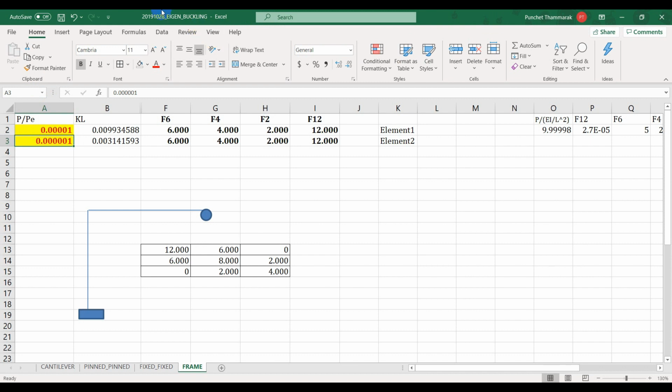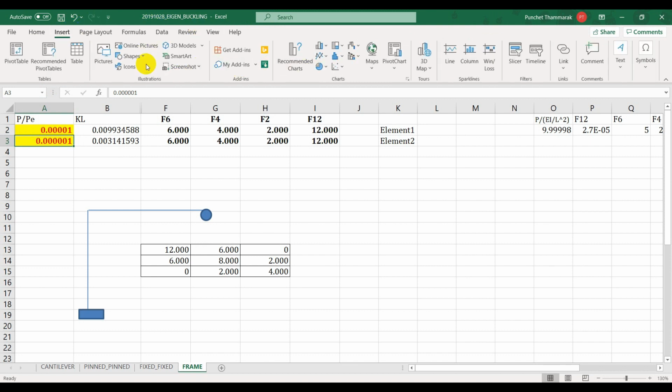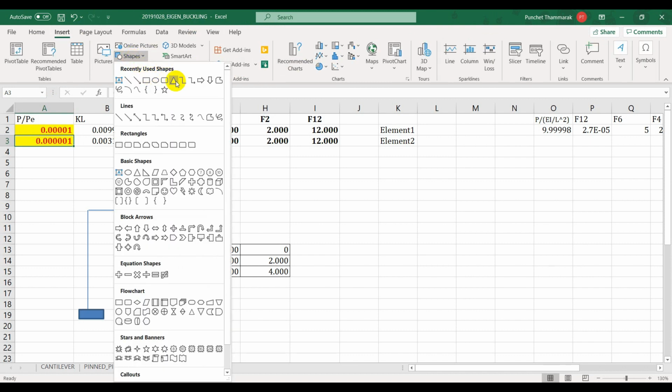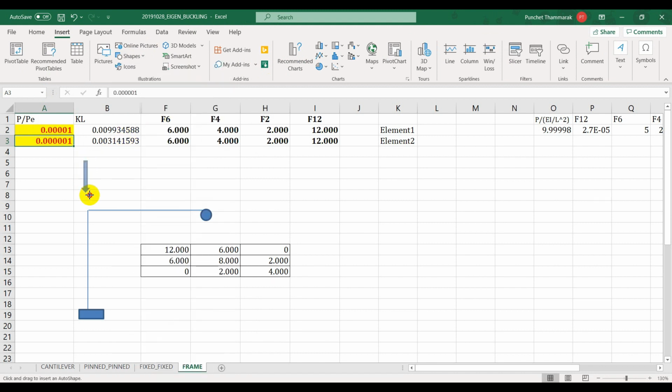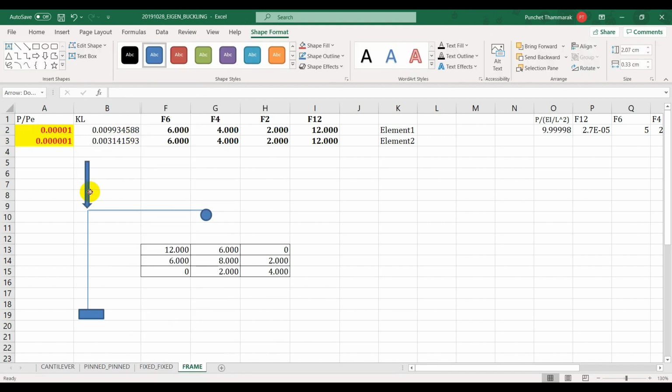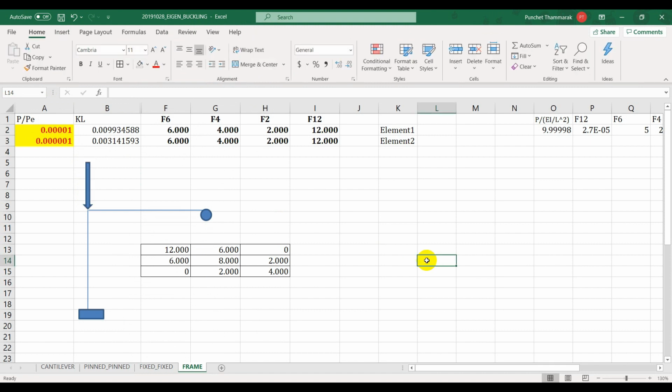And let me emphasize here that the Eigen buckling problem depends on how you apply the load. For this case, you have just one column. It's not possible to apply axial load to the other element. But sometimes you have more than one column in the system, and you might apply the load to the columns differently. You have different magnitudes, but it sticks to one pattern.